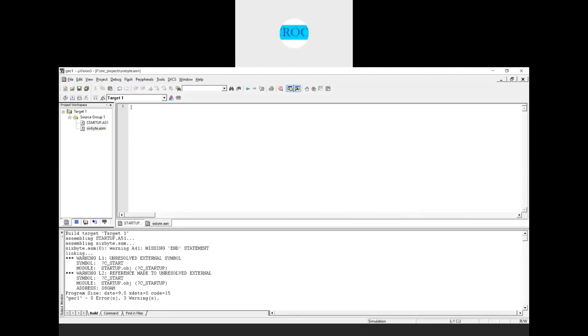Now the first thing is we need to follow those steps. What are the steps we have? The first one is MOV. We need to initialize the TMOD register, comma, hash. If I'm using timer 0, I'm initializing it so that the timer is operating in which mode now? Maybe now timer 0 is selected in mode 1 there, right?